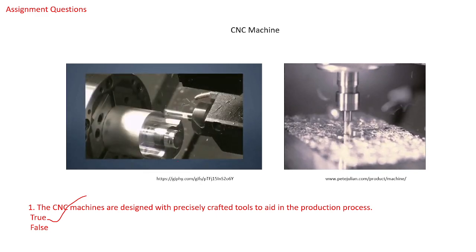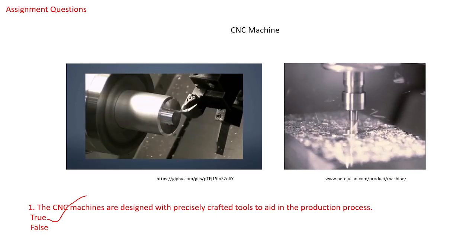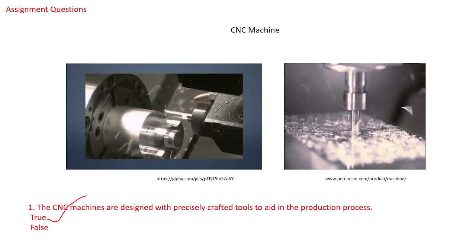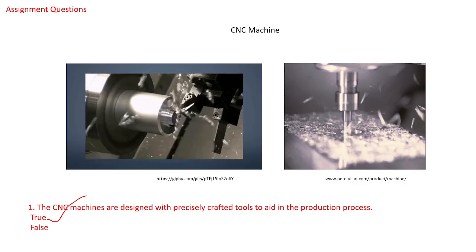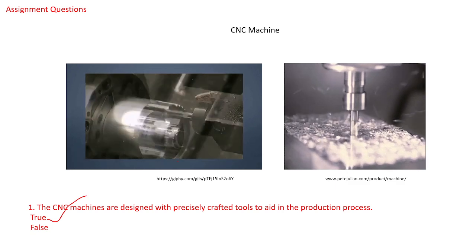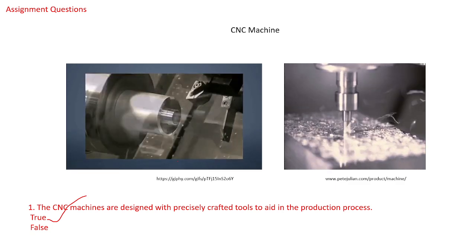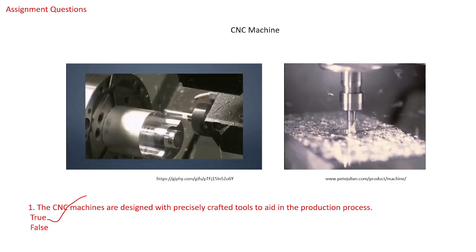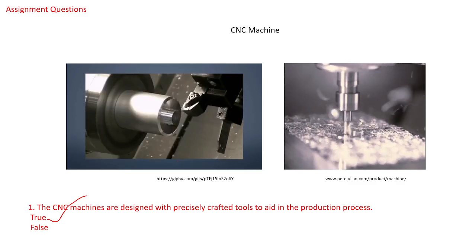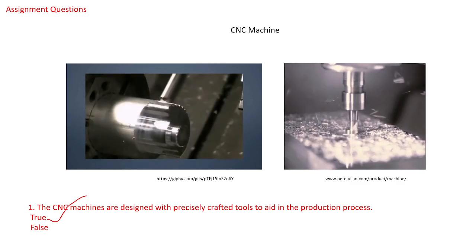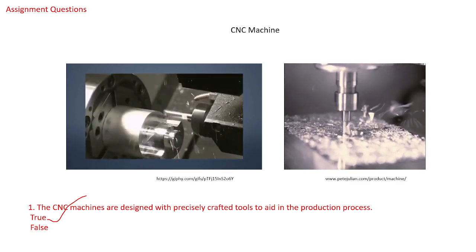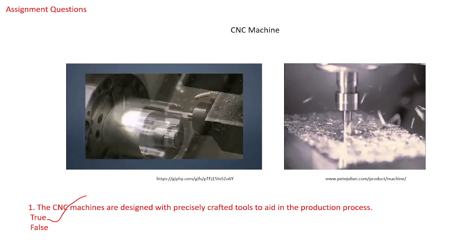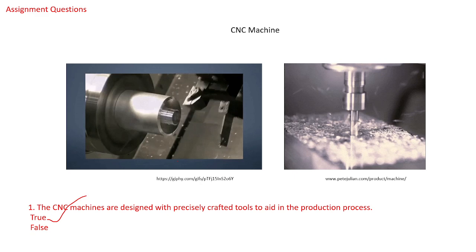As we are talking about CNC machining, obviously it's versatile and compatible with various materials, right? The same steps are followed in the CNC milling process also, starting from preparing a 2D or 3D CAD model as per our requirement, like technical drawings given to the operator. You have to mention the critical features or dimensions of the part, the tolerances, the finishing preferences or construction lines in your CAD design as per your requirement. Then export your design to a CNC compatible file format.